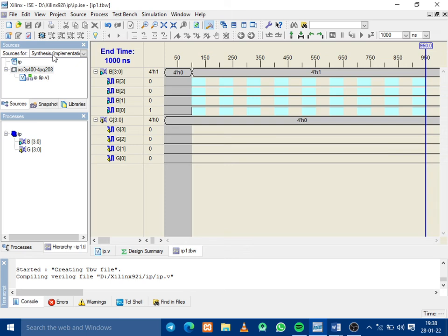This is the Xilinx ISim simulator. Now we have to simulate our code, so click on this plus sign, again click on this plus sign. You have to generate self-checking, which means these inputs are checked internally. So I click on self generate check.